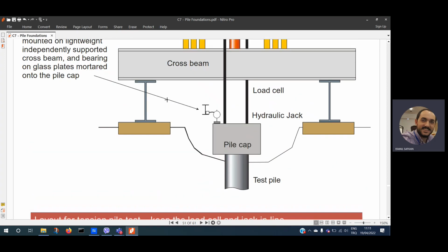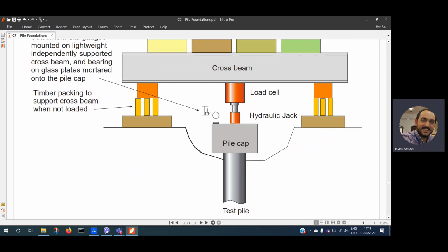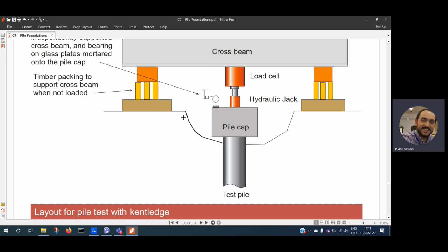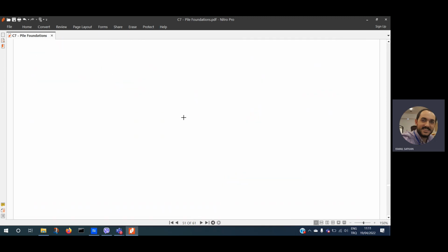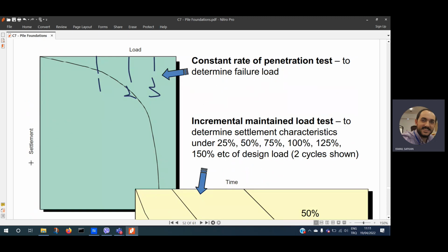For the newcomers, you remember the pile test? We apply a test and we monitor the force through the load cell and displacement through the gauge. Then we have the force-deformation relationship. This is settlement, the deformation, and the x-axis is the load. Initially it behaves elastically and then it goes plastic. Considering all these levels, what point do you think